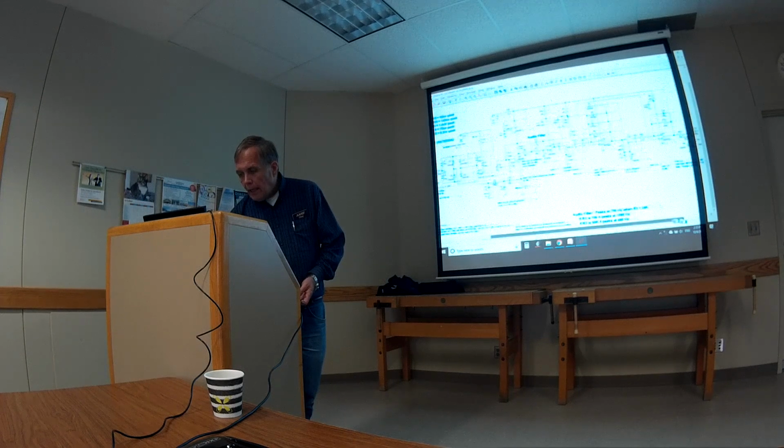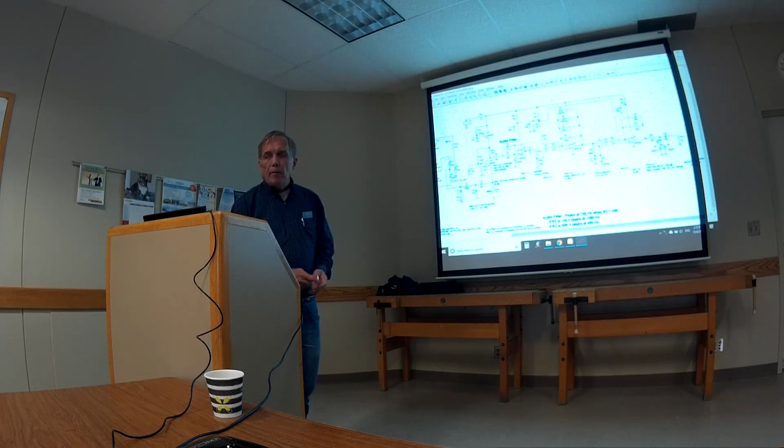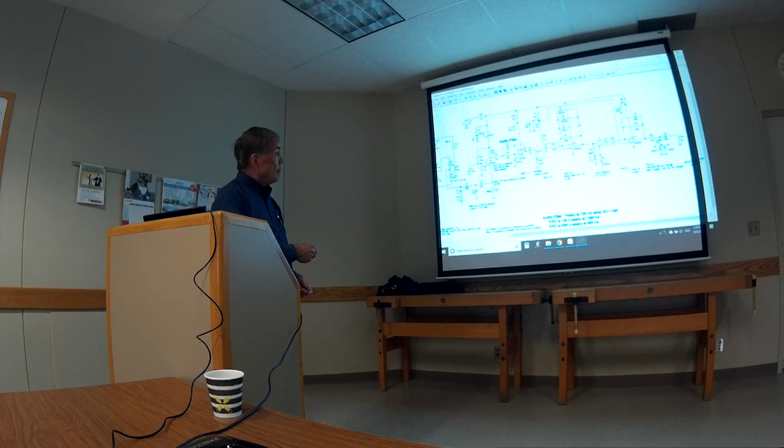I did it and kind of predicted, because I needed about 100 dB of gain between the antenna and the audio, okay? And I wanted to see what this would set up with these values, what kind of amplification I needed. And so I could look at each one of them, look at the waveform, and see how big it is compared to how big the antenna was at the antenna. And I could check out the gain right here. The gain, since the diplexer, was 51 dB. And then I go on to the next one.